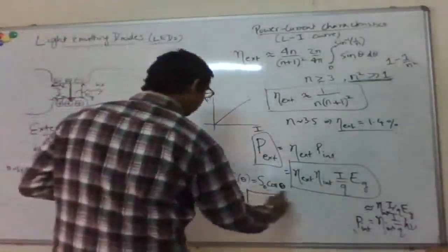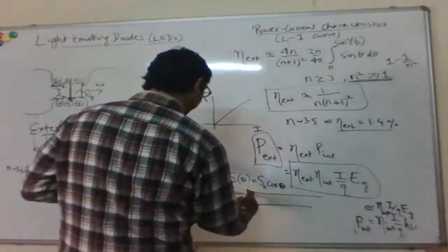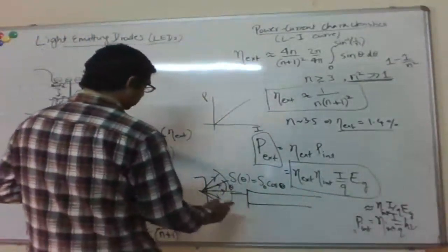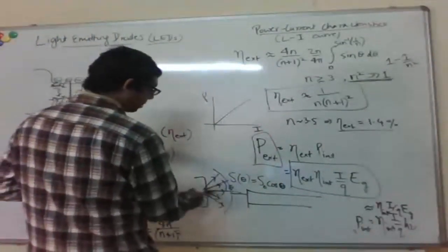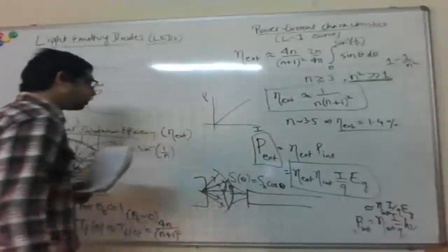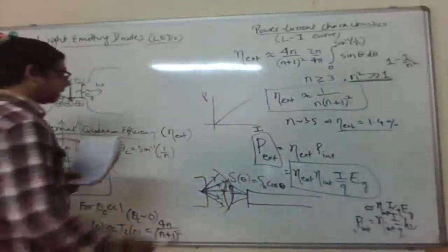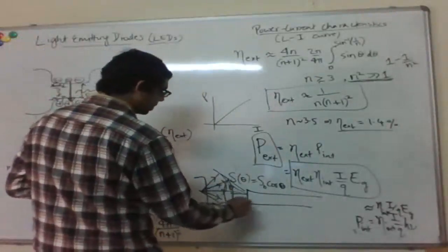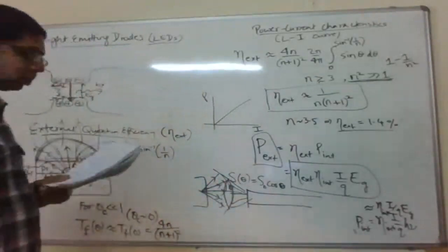Okay, and remember now, let's say for communication, we want to couple this into an optical fiber, right? So for a laser, when all the rays coming out are parallel, it's easy to use a lens and then focus it into the fiber. But for this diverging kind of source, the coupling efficiency into the optical fiber also goes down.